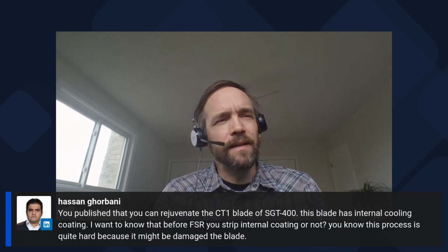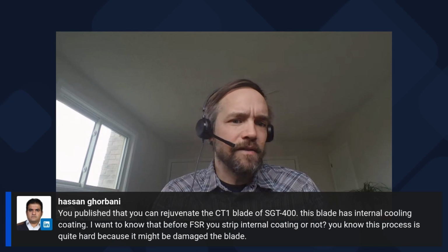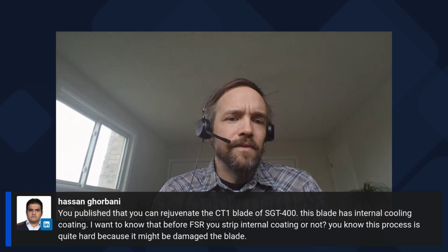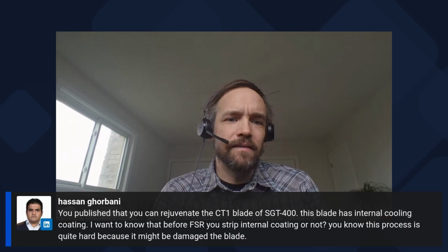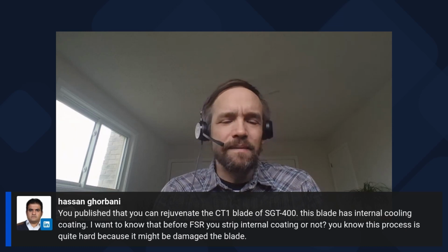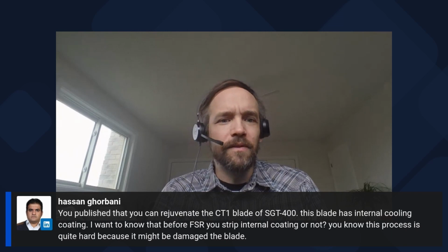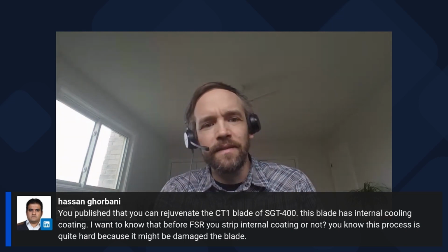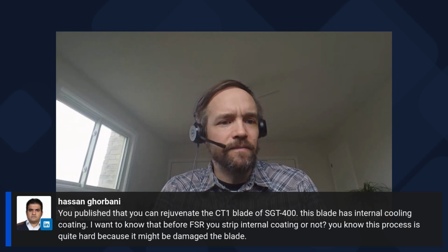Sorry, just going back to the last part, the NDT, to confirm that rejuvenation has been successful. We don't apply non-destructive testing to validate that the material has been restored, because we do have material that we can process with the set. There are some NDT methods that can by proxy determine whether or not FSR has been successful, but the more direct measurement of that is with material that's destructively tested. So that's what we tend to do for qualification.